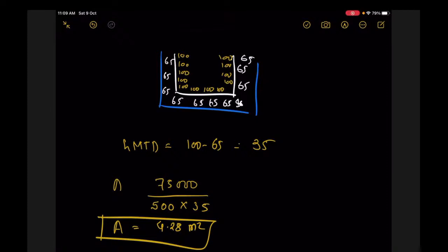So it is not that we have to stick always to that formula. We have seen when delta T1 is equal to delta T2, which is a special case of a counter current heat exchanger, at that time you are getting 0 by 0, so you can apply L'Hospital's rule there mathematically. And if you see the physical meaning, everywhere the temperature difference is the same, delta T is the same everywhere. So why is there a requirement of calculating a mean again?